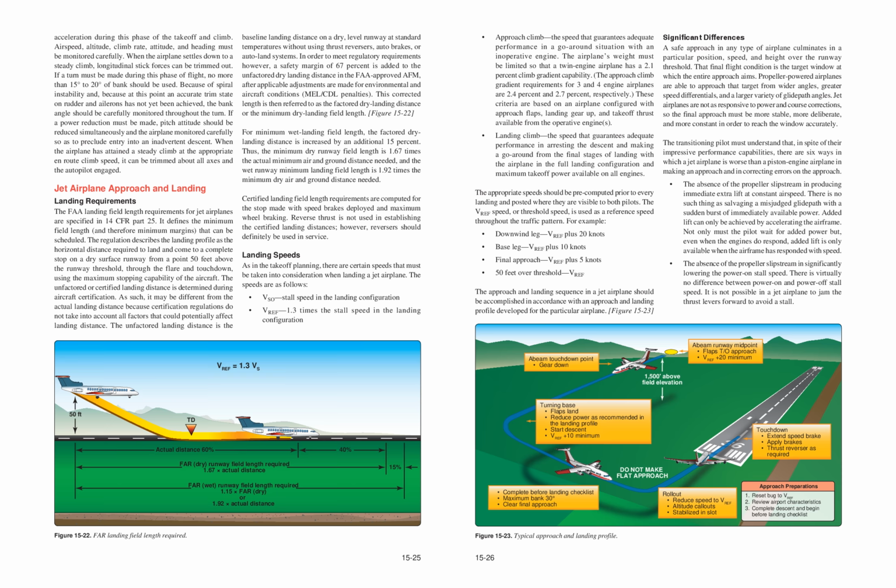Landing speeds. As in the takeoff planning, there are certain speeds that must be taken into consideration when landing a jet airplane. The speeds are as follows. VSO, stall speed in the landing configuration. VRF, 1.3 times the stall speed in the landing configuration. VRF equals 1.3 VSO.